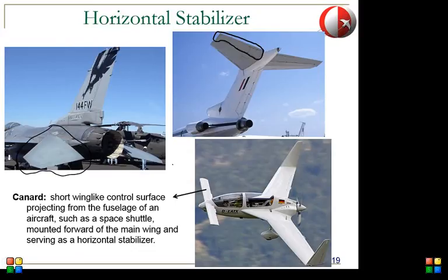And that's because this is a supersonic aircraft. So to be able to control the aircraft at supersonic speeds, you have to move the entire horizontal stabilizer. Otherwise, just an elevator like this is not effective at very high speeds. So this is just one of the reasons why flying at supersonic speeds is very difficult.